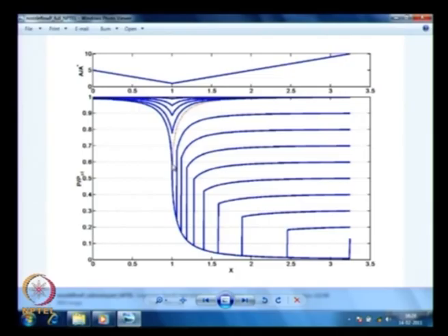After that, I am going to have different curves. If I pick this Pb by P naught 1 as 0.9, then it goes through this up to here. The shock is sitting at this location, and from there it is jumping to some other pressure and going through the remaining part as a subsonic solution. And you can see as I decrease my back pressure, the shock is going more and more downstream.